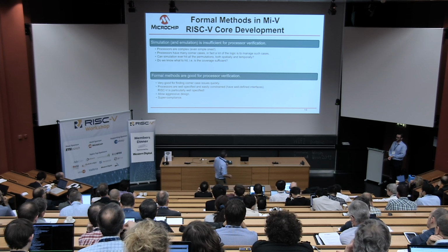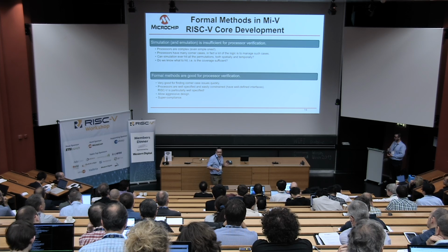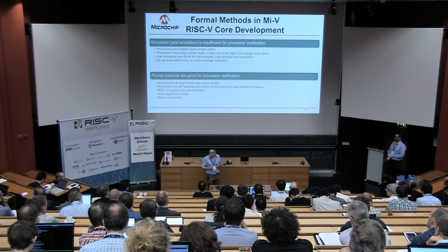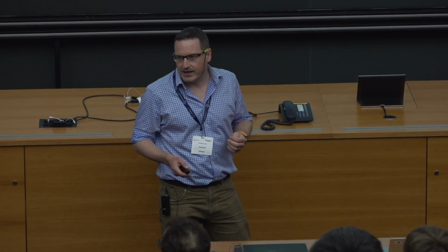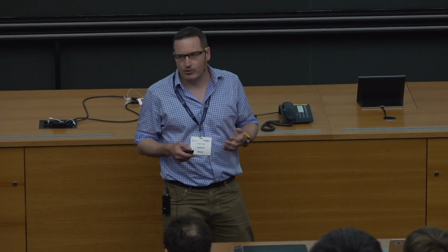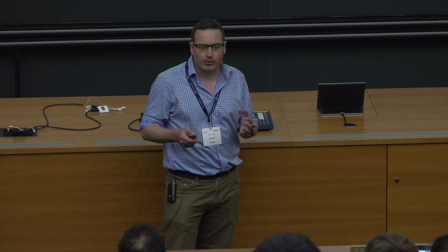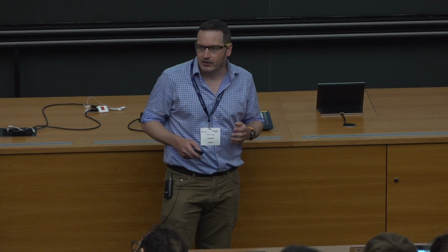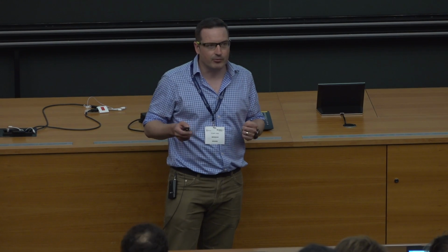One of the other advantages of using formal methods is that when we're doing processor design, we may be somewhat pessimistic about certain things like buffer sizes, queue lengths and so on. But if we know for sure that we can absolutely prove whether something works or not, we can be a lot more aggressive in those techniques. We can also use the formal tools to help us understand the limits of things. We can ask, can all the buffer locations actually be used? If they can't, we can make our buffers smaller, or perform other optimizations in the design.